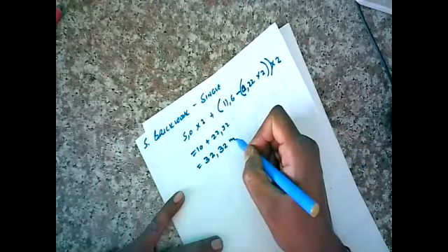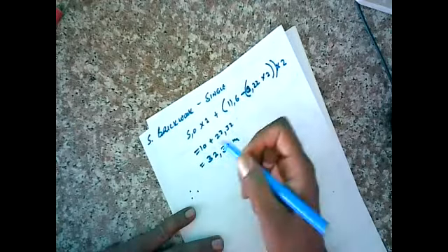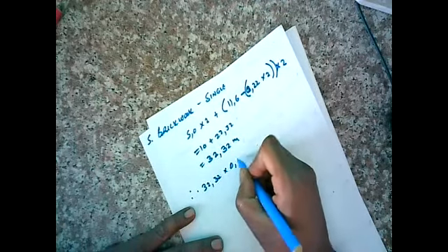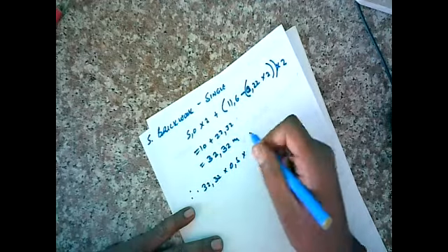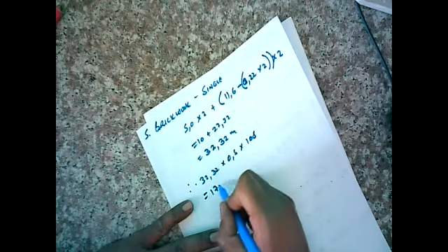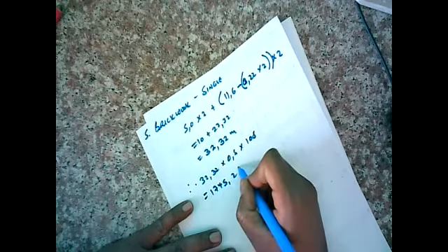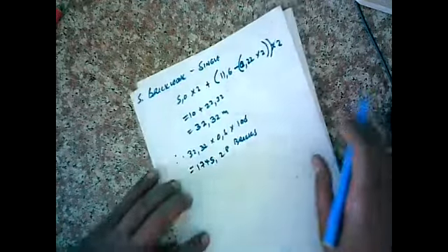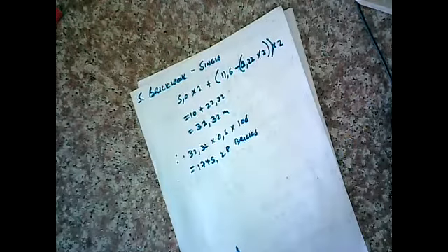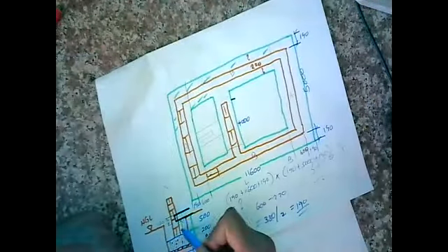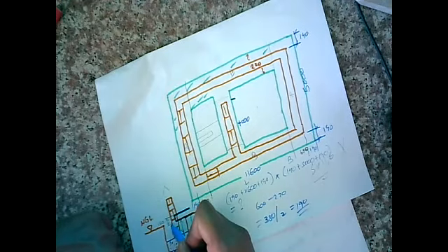All right, we know the meterage, and we're saying now, therefore, how many bricks do we need? 32.32 times 0.5, because that's how high the wall is, times 108, because it's a single brick wall, and we're getting 1745.28 bricks. All right, now moving on. We put that part on. Now let's put this part on.